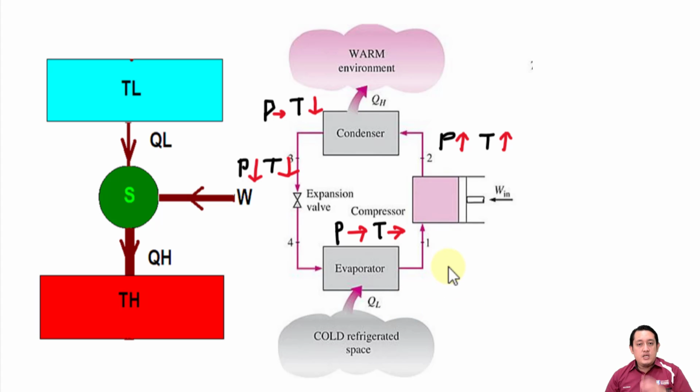It is very important for the refrigerant to become a gas before entering a compressor, because normally a compressor can only handle gas, not liquid. If a liquid enters this compressor, there is a high chance that the compressor will not work properly. So we don't want that.